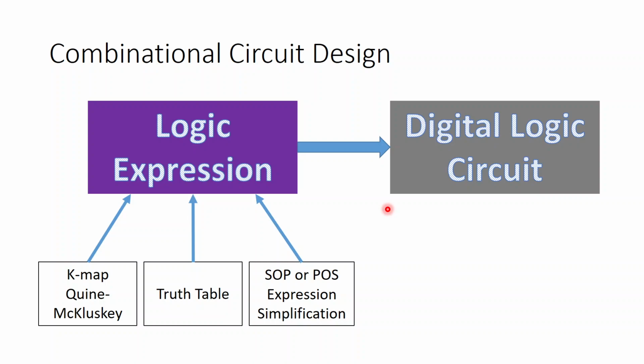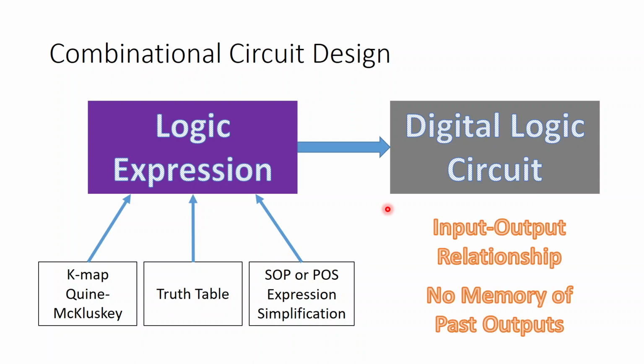Now this sort of a thing, where we have simply a circuit using logic gates, where we are noting down the input and output relationship without any memory of past outputs, that means the present output will not depend on what the past state of the system was, what the past outputs of the logic gates were. It will simply depend on what inputs you have given just now.